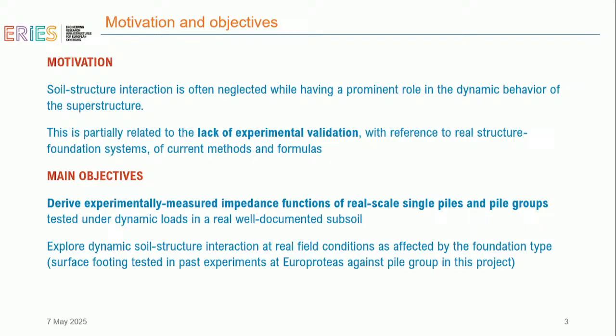First of all, soil structure interaction is often neglected while having a prominent role in the dynamic behavior of the superstructure. The new upcoming Eurocode 8 is coming to fix this problem. A big thing is that whatever has to do with SSI partially lacks experimental validation, with reference to real structure foundation systems or current methods and formulas.